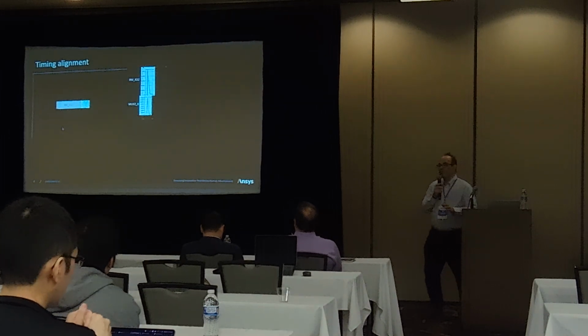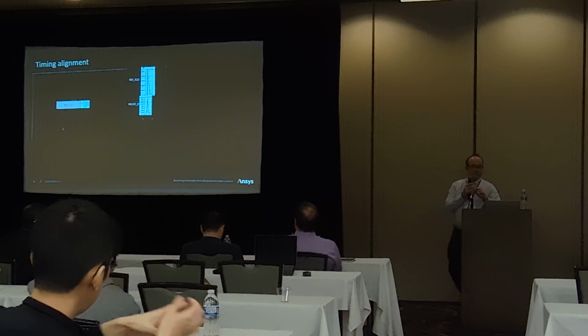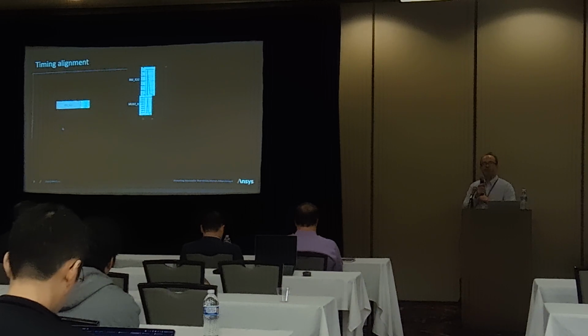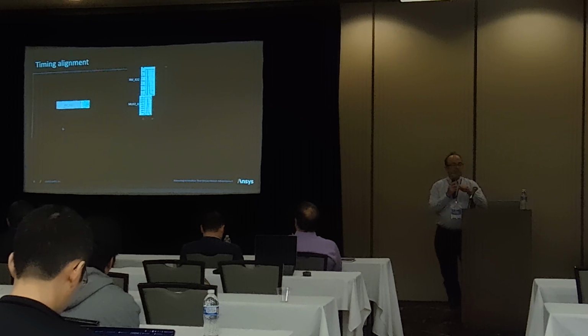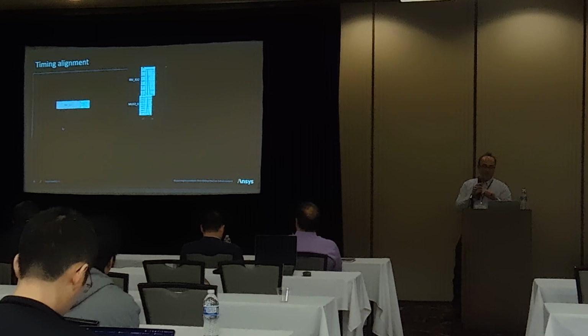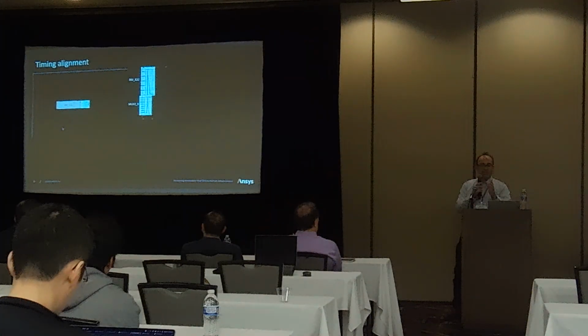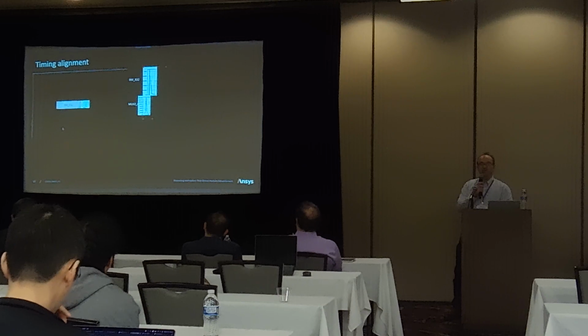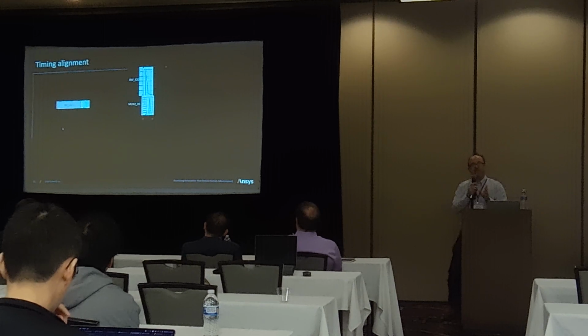One problem of simulation is, let's say we have a very simple section of the design. On the left is the red box, an inverter cell. On the right, there is a neighbor. When they both switch, they come from the power rail, maybe the ground rail, and utilize the same resources. So in a way, they affect each other. You can create a case where they switch together, creating a peak-aligned mode, which stresses the design much more. Or they may be shifted a little bit, or even shifted to the other side. So all three possible vector generations within a clock cycle can happen.